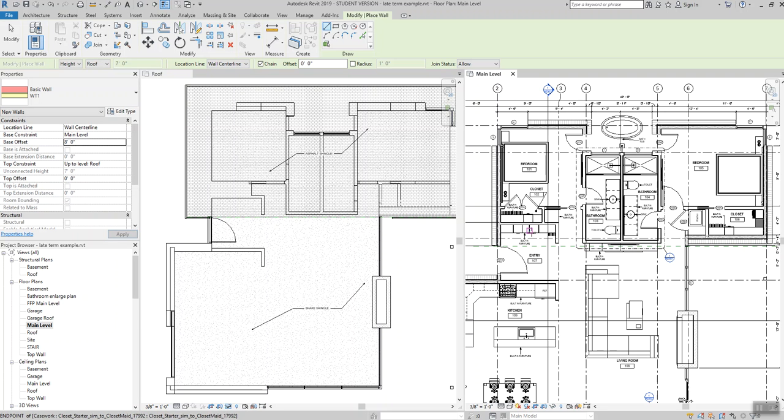Enter. And you're thinking, 8 feet? Why 8 feet? Well, we want this to be open right here. So essentially what we're saying is start the wall at 8 feet, take it up above the roof, and that will create that high little wall up there. Essentially what they would do in real life is there would be a beam or something that goes across here that allows there to be openness below, and then the wall would be built above that.